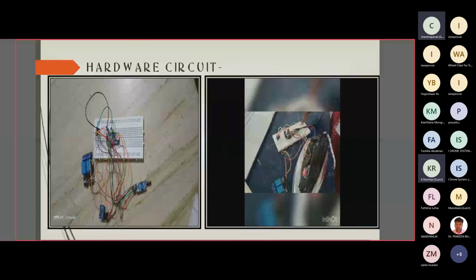Here I am going to explain about the working. It's a brief explanation. In our project, we have used two Arduino interface sensors, like vibration sensor and gyro, accelerometer sensor as an input side. We have used Arduino Nano as a microcontroller, which controls the whole circuit of this project. Arduino IDE is the software platform where we coded the program. It is to control the sensor. Using vibration sensor and gyro sensor, we have got the values and used if conditions to switch on, switch off the relay in an automatic manner.